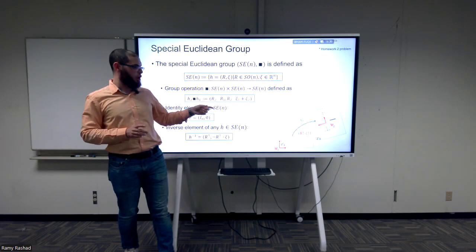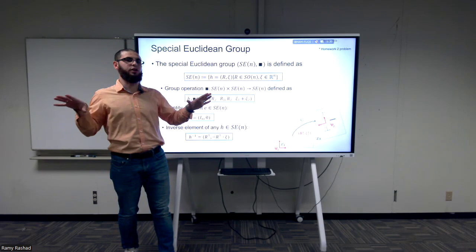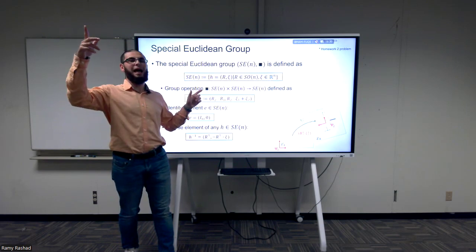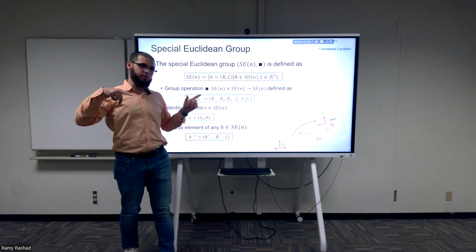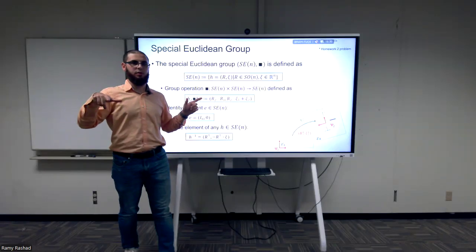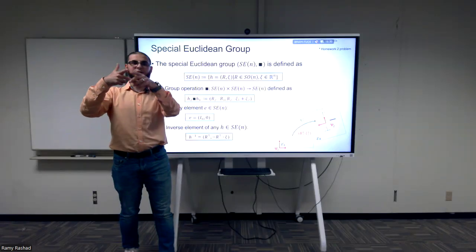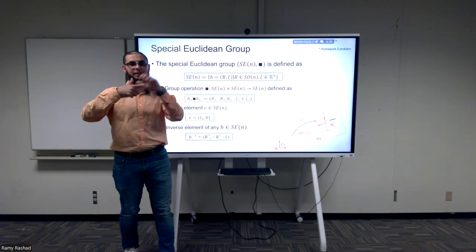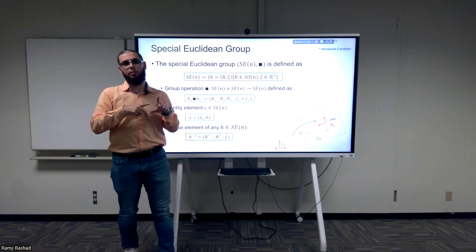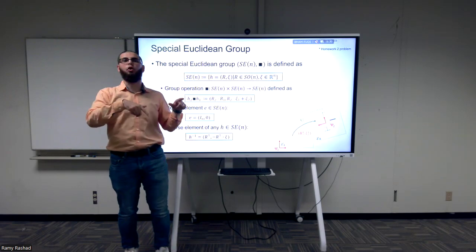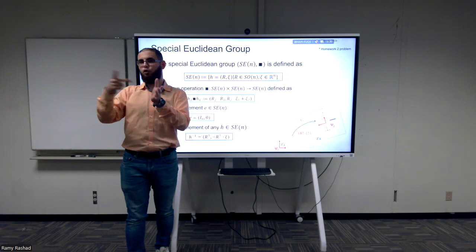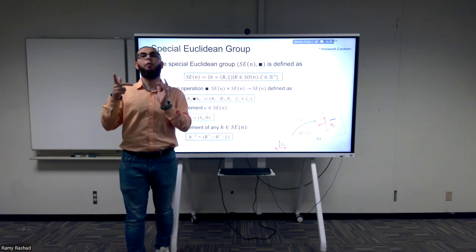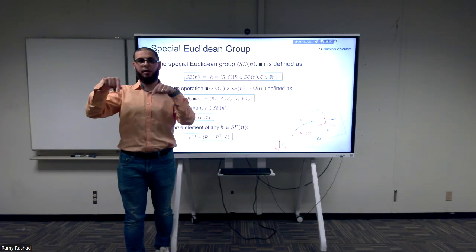The chart that we're talking about, there are different charts. The first chart is from the abstract Euclidean space to numbers by looking at the frame. The second one is having a chart for SO3 itself, which is the idea of not using a 3x3 matrix to represent this rotation but using only 3 numbers. And this is something we're going to be proving also in the homework, inshallah. I have a 3x3 matrix representation of a rotation, right? Of orientation. How many degrees of freedom do I actually have in these 9 numbers?